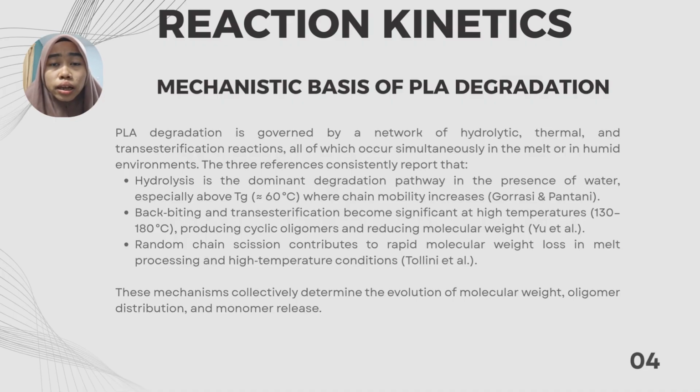Yu et al. showed that at high temperatures, backbiting and transesterification also occur, forming cyclic oligomers. Tolini's model adds that random chain scission becomes significant during melt processing. So overall, PLA degradation is controlled by hydrolysis, transesterification, and thermal scission happening at the same time.